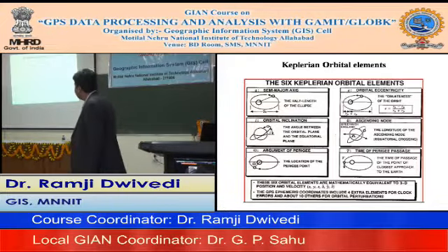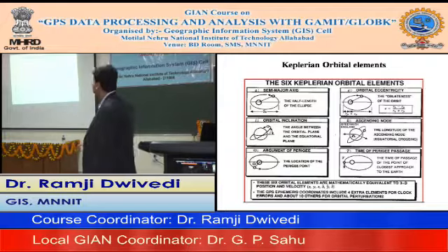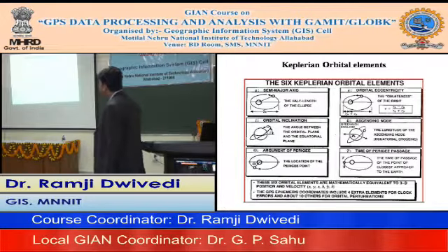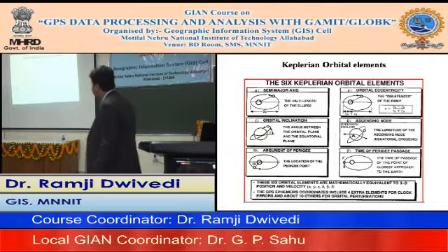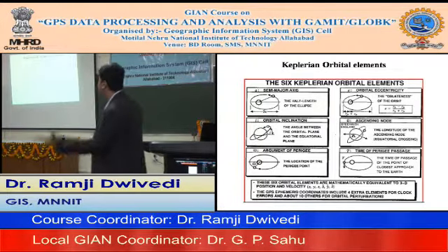Please remember, this is why we discussed the reference systems in the first part: the motion of the satellite we are computing in terms of coordinates is not in the Earth-centered terrestrial system, it is in the Earth Centered Inertial system. We are measuring the satellite coordinates in the ECI system, and we have to rotate it further, using a rotation matrix, to convert to Earth Centered Earth Fixed.